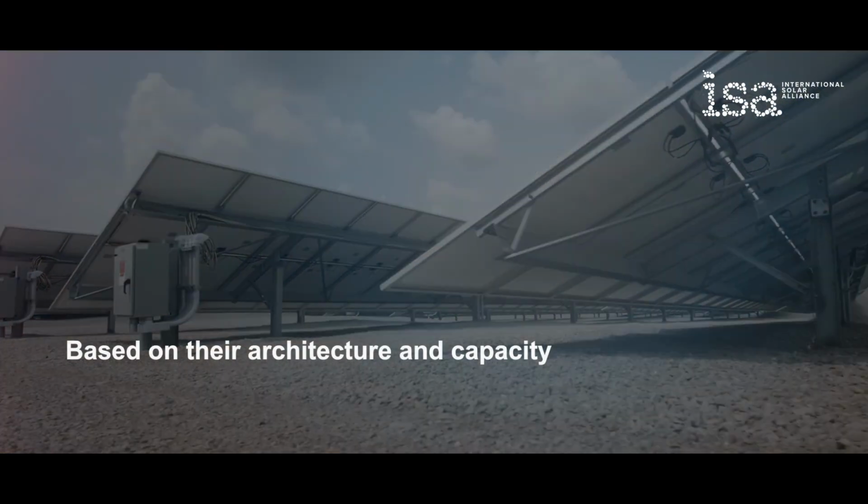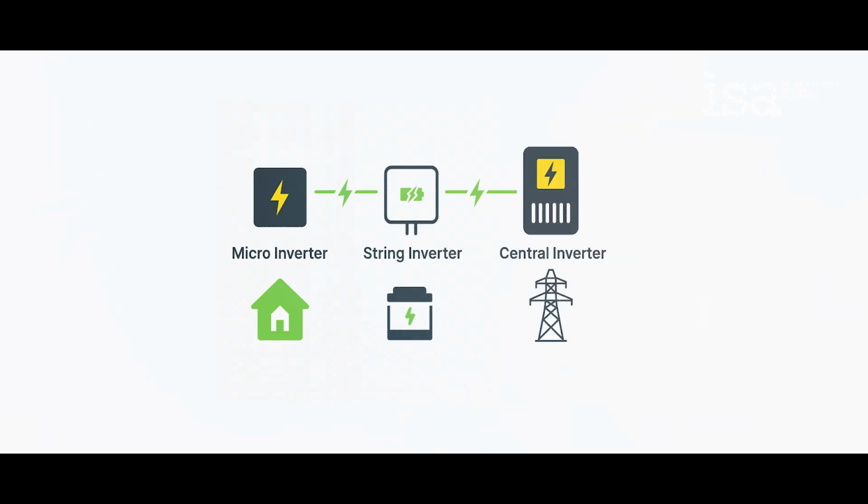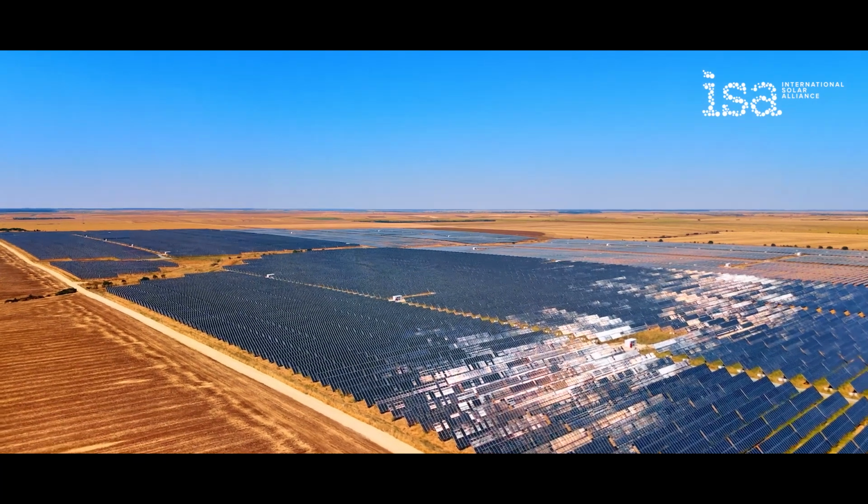Based on their architecture and capacity, micro-inverters, one per module, enable module-level monitoring. String inverters connect several strings of panels with MPPTs, ideal for rooftops. Central inverters, used in utility-scale projects, handle high voltage and current inputs as in large power plants.